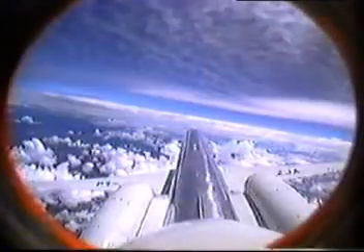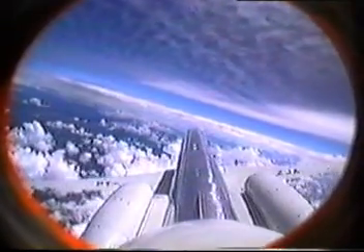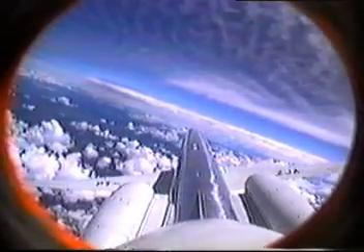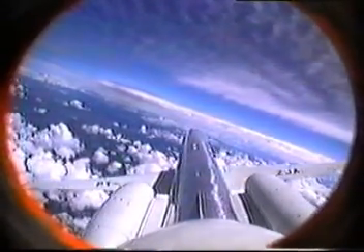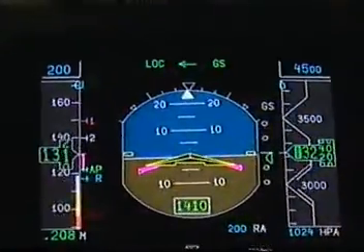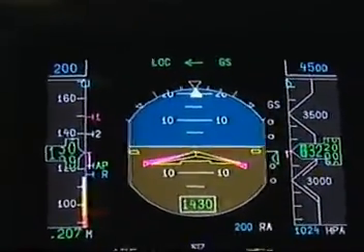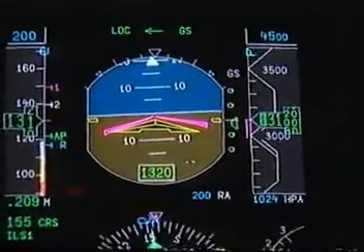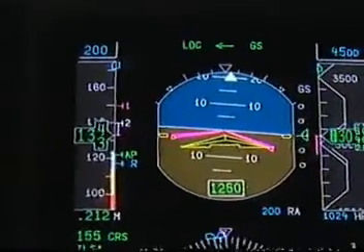If you suspect you are entering the backside of the drag curve, make a firm decision and simply add power with determination. Embraer does not recommend any approach with speeds other than those published in the airplane flight manual. Flying in the AFM speeds and keeping the flap maneuvering speed published in the airplane operations manual will maintain you in the safe region of the curve. Actually, flying the Embraer jets according to the rules gets you into the safe side of the curve. These aircraft have excellent handling qualities at low speeds.